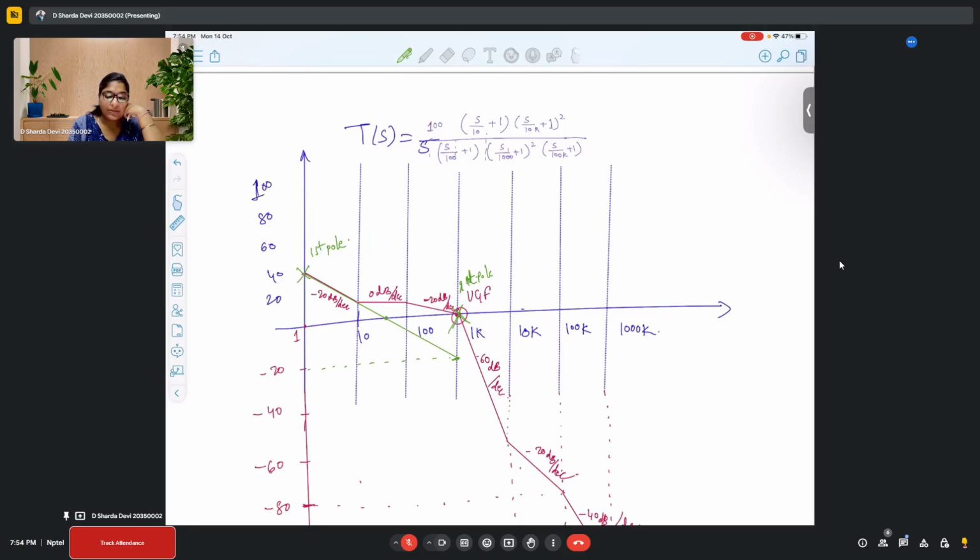So when that is the case, things will change slightly, because now when I'm starting from 1 and reaching till 1000, I say there is a 20 dB per decade slope, so it is crossing at 100. If we start from 0.1, we reach one more decade down, minus 40, right? Yes, true. That's what I meant.